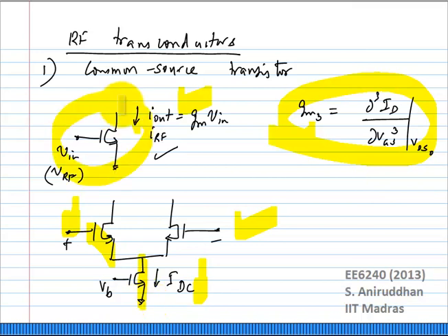If you have a common source transistor like this, you can similarly define the bias at the gate, right, using a current mirror. So you will have a pseudo differential or a single-ended configuration. Even if you want a differential configuration, we also looked at the pseudo differential case, where you can have two of these with plus VRF by 2 and minus VRF by 2.